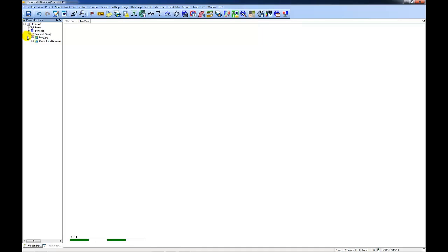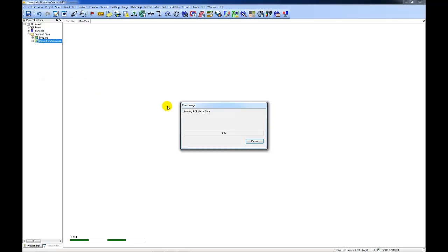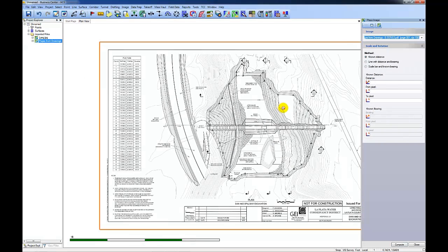We give you 4 different ways to reference or scale PDFs and images. The most accurate way is to georeference the image and type in actual control points. We also could type in a known distance. The second most accurate way is distance and bearing. Distance and direction on north arrow is a great method for performing takeoffs. We will use that method, but we could enter some of these northings and eastings.